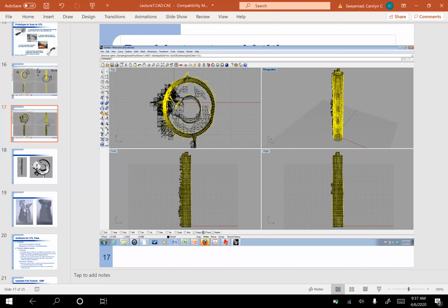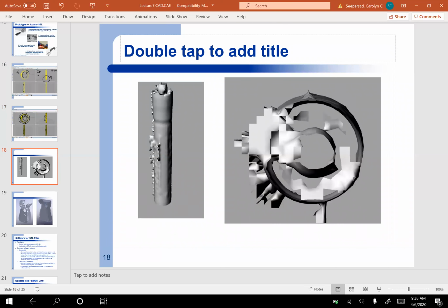And other aspects that we can't see very well, like the top, don't really get filled in at all. Here you can see, if we look closely, that there are lots and lots of areas that aren't watertight, right? We've got STL triangles here that are not connected to anything else. So they're edges with only one face. And we know what that means, right? That it's not watertight.